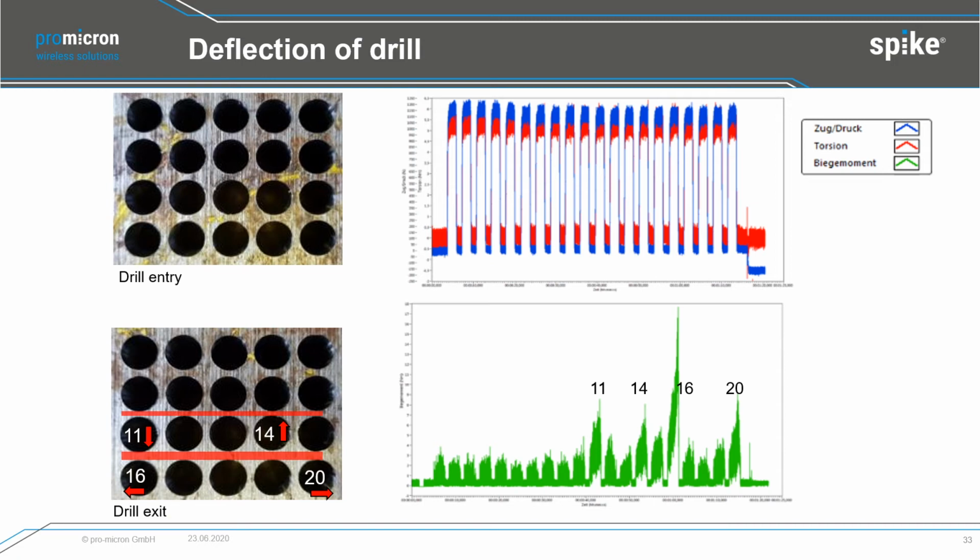And we told him that we should not only look at the tapping operation, we always need to check the pre-drilling operation before as well, because maybe the pre-process has a bad condition or is not perfect. So the after process, the tapping, will cause tool breakage and then machine downtime.